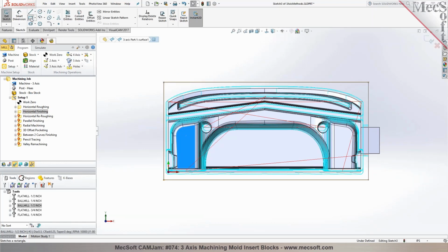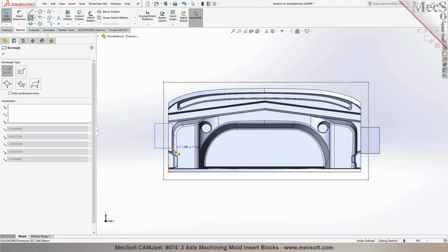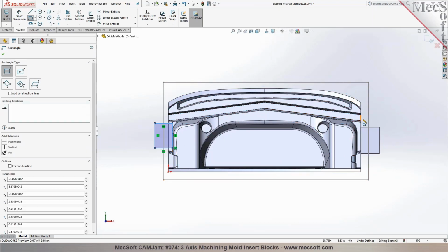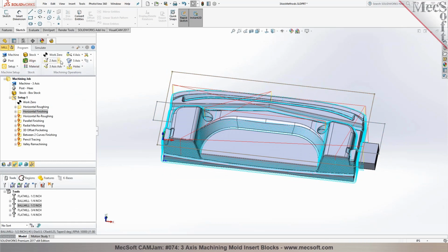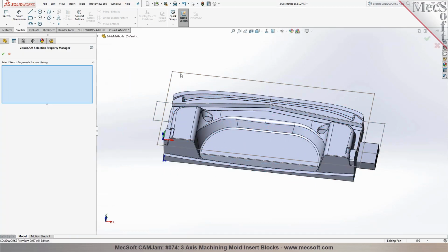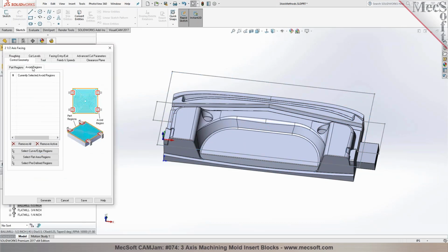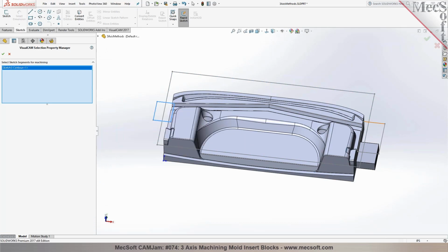So I have the sketch drawn in here. Now I could program a 2-axis facing, and I'm going to say select curves. I'm going to select this chain right in here, and then for avoid areas, I'm going to select these 2 boundaries in here. So I have these selected, and I can specify a tool for it. And when I generate the toolpath, it'll automatically treat those as areas not to be cut into. So that's the way we handle avoid areas.